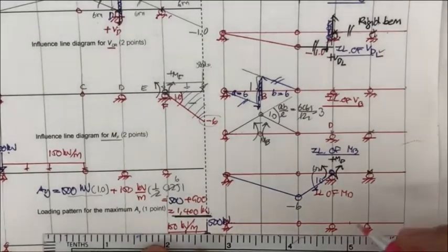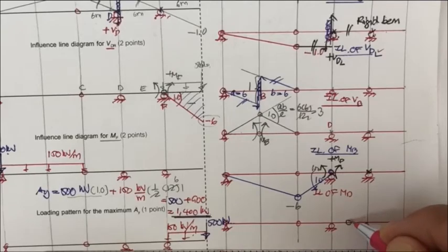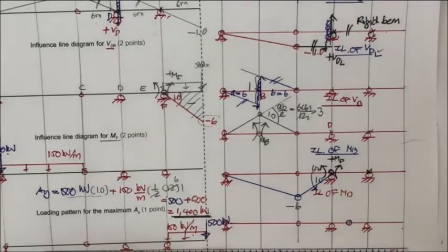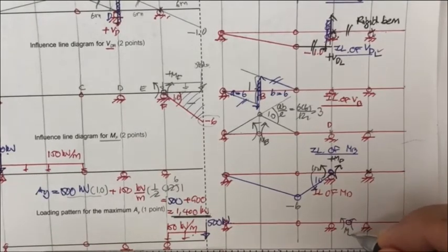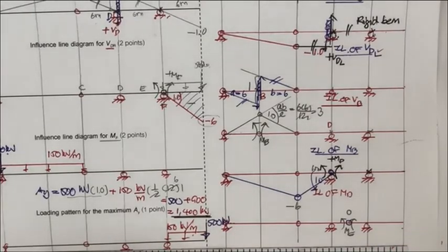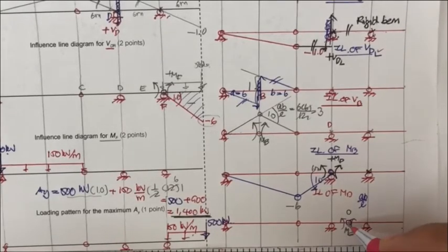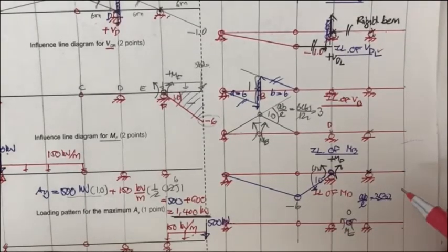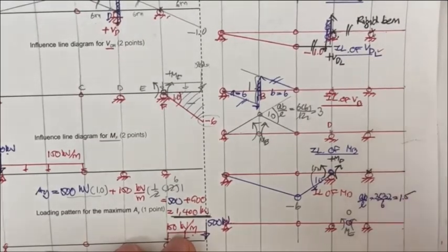You eliminate the resistance to M sub E, and then you put the positive moment M sub E to drive this one up, with AB over L. This one is A, this one is B. It's going to be 3 times 3 divided by the total of 6, and you get 1.5.